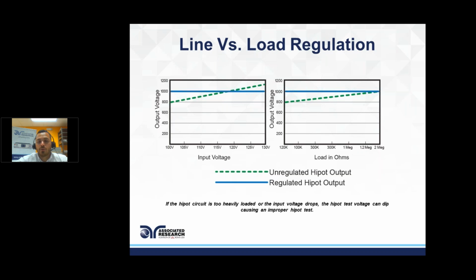They're starting to say you no longer need 500 VA, or at least we're in the midst of that. We actually have some of our colleagues on certain standard boards, and they're trying to get rid of that 500 VA because it's outdated. It's no longer needed. With the technology we have today in Hipot testers, your output, for the most part, can drive and stay consistent.